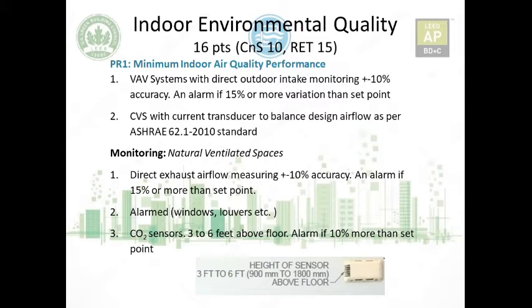Now the third thing is that you have to install CO2 sensors. Let's understand why we need the CO2 sensors. Carbon dioxide is produced when people breathe. Each exhaled breath by an average adult contains 35,000 to 50,000 parts per million of carbon dioxide, which is 100 times higher than the amount typically found in the outside air. So if the building ventilation system is not adequate, accumulated CO2 can cause health issues.